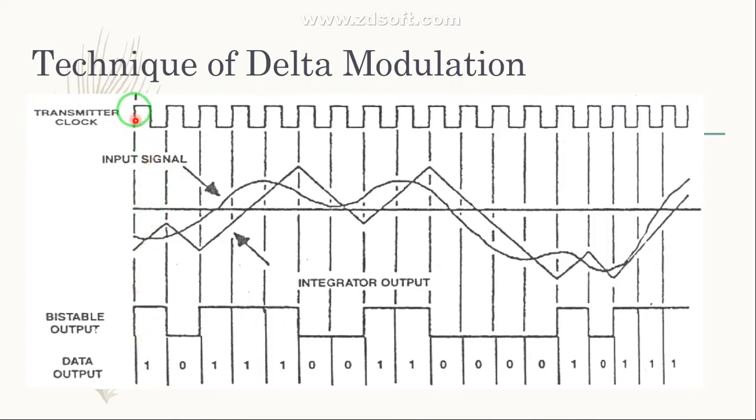This is the transmitter clock, and this is a rising edge, and this is a falling edge. So we are going to latch it at the rising edge of the transmitter clock. Then the latched 1 output of this D flip-flop is translated to -4 volt by the unipolar to bipolar converter block.